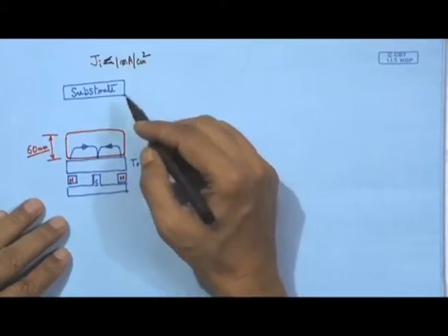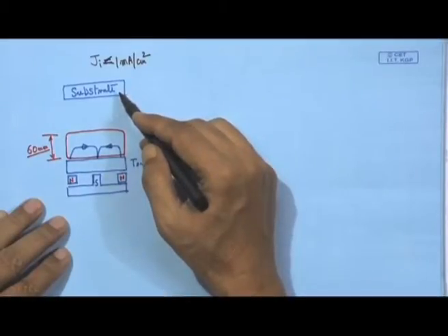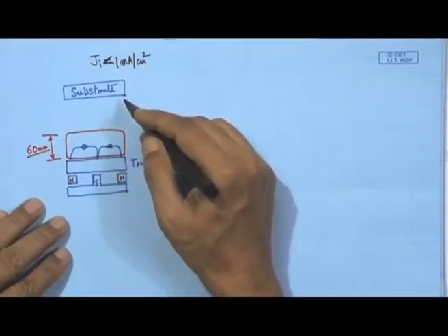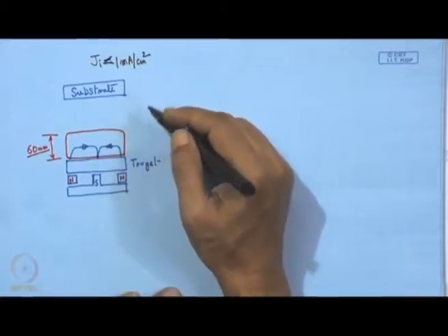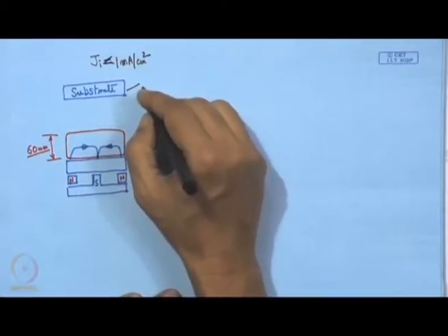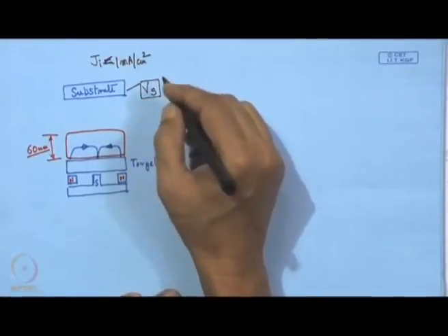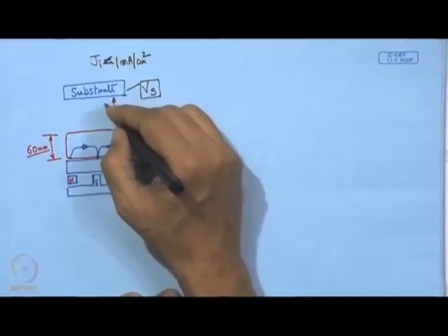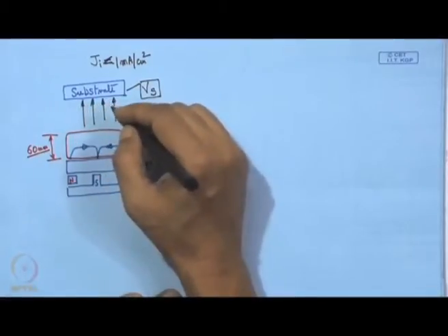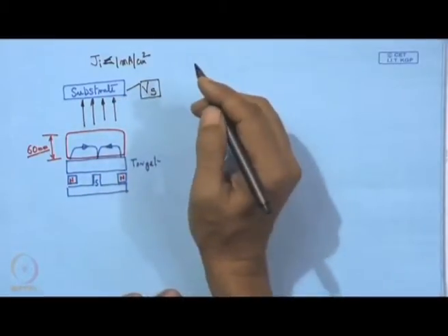This lack of plasma density for a substrate outside the plasma volume can be compensated, perhaps by increasing the substrate bias Vs, so that we have high ion energy, which is expected to cause strong bombardment on the surface.